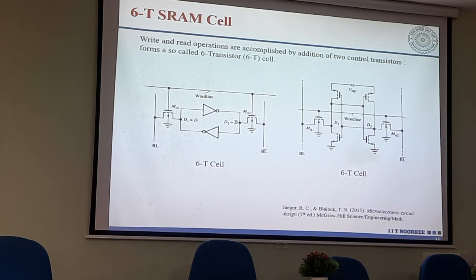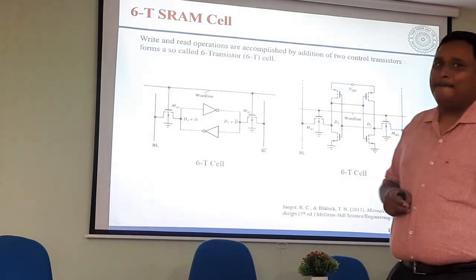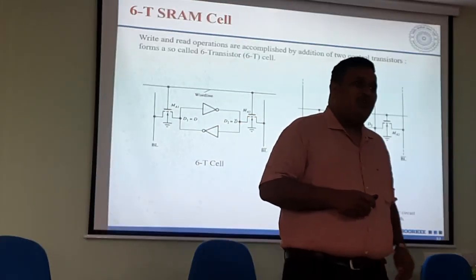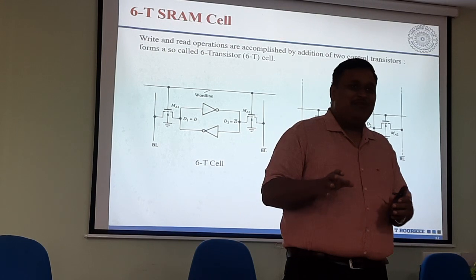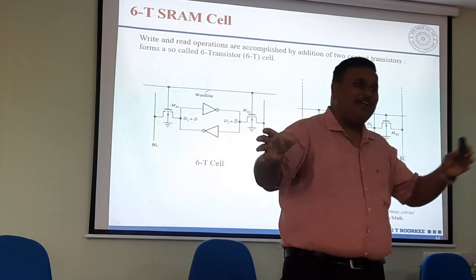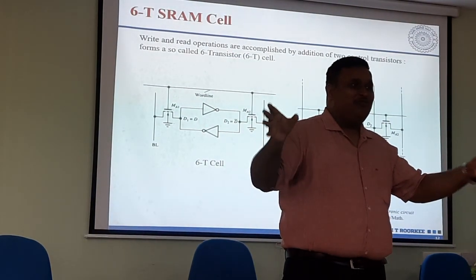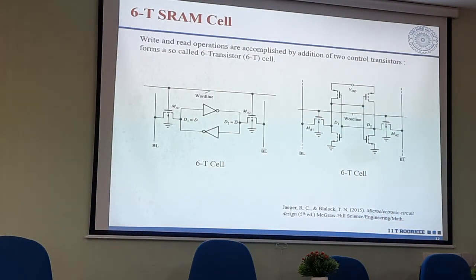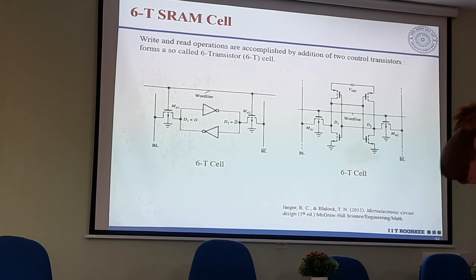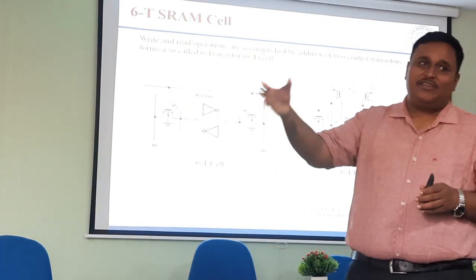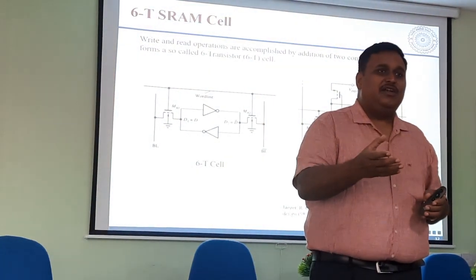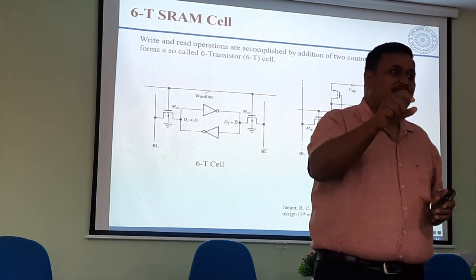Sir, MRAM doesn't interact with Earth's magnetic field. Is it affected by it? When you talk about Earth's magnetic field, people are even more concerned about one MRAM affecting another MRAM, right? This would have been true if we were switching the MRAM using a magnetic field only. But we are no more switching those MRAMs using some external magnetic field. We are using only the current-generated magnetic field to switch these devices.